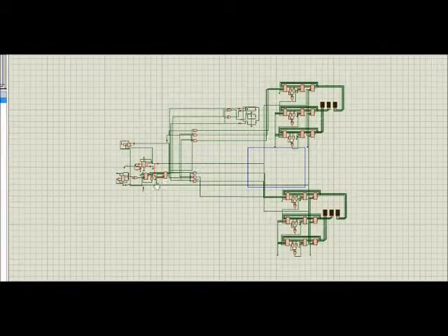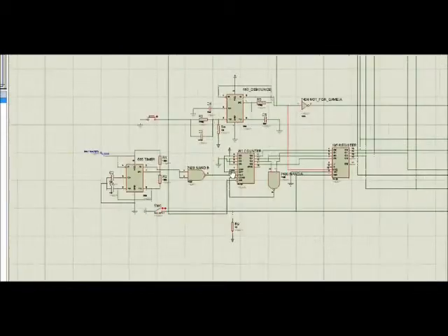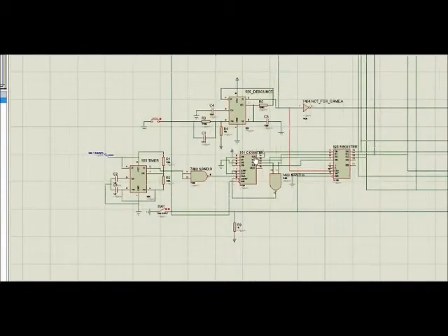Now let's take a look at the operating circuit of the game. The operating circuit has four parts. Firstly, we have the random number generator that generates the random point scored by a player when he presses the game switch. This part of the circuit consists of three major ICs: a 555 timer, a 74161 synchronous 4-bit binary counter, and a 74195 parallel access shift register.